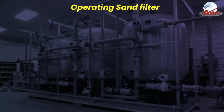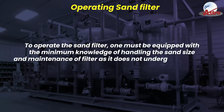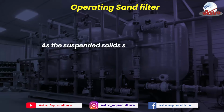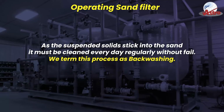Operating sand filter. To operate the sand filter, one must be equipped with the minimum knowledge of handling the sand size and maintenance of filter, as it does not undergo continuous cleaning process as in drum filter. As the suspended solids stick into the sand, it must be cleaned every day regularly without fail. We term this process as backwashing.